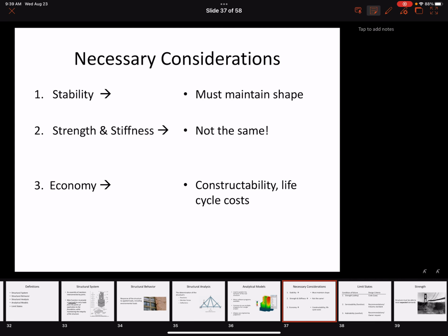I remember what I was going to point out here. This is back to the stability thing, when I said that the structure needs to be able to return to its original position after loads are applied. You all know this already, so who remembers what that is tied to from mechanics of materials? The proportional limit? You're on the right track. The stress-strain curve, and what does that proportional limit distinguish between? Before it returns to its original state, or the point where it's not going to be able to? Once you get beyond that, what happens? It'll have permanent deflections. It's elastic versus plastic behavior. Excellent, so elastic behavior.